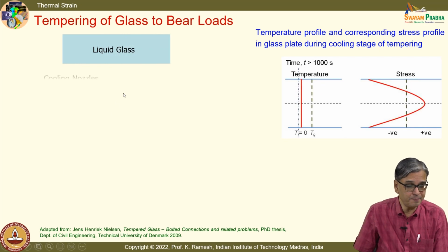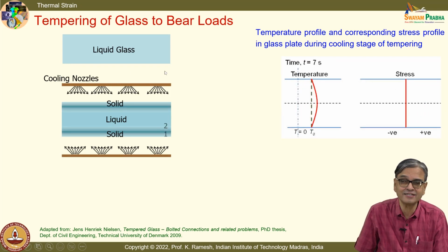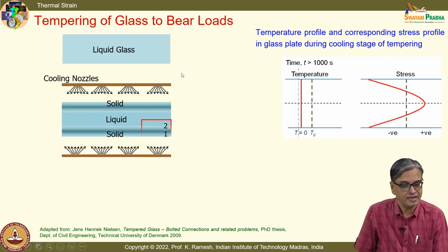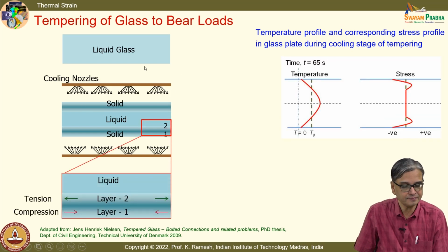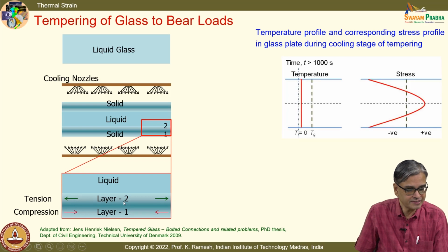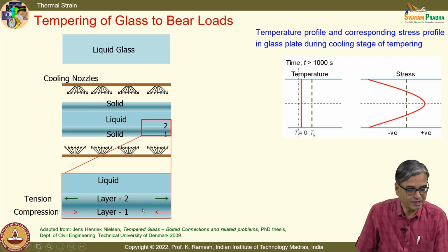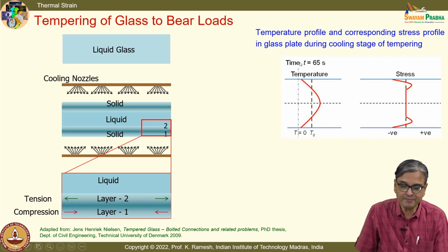And you temper the glass, you introduce intentional stresses while the glass is being fabricated. What you have is a liquid glass, and then you have cooling nozzles. The outer layer gets cooled first, and this will prevent the inner layer from coming back to its original position. So you have compressive stresses developed on the outer layer, and then a tensile stress developed inside, and as a function of time, this is what it shows.